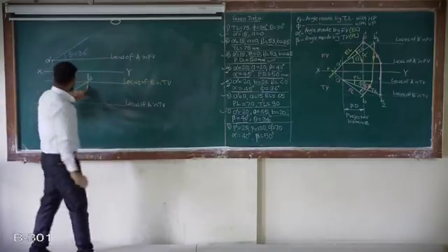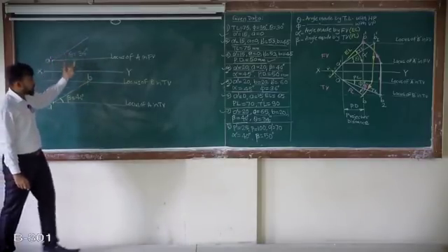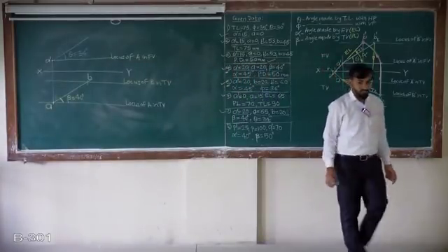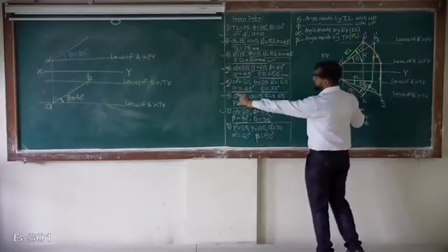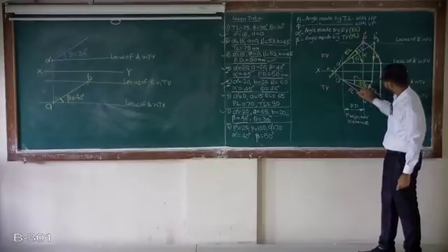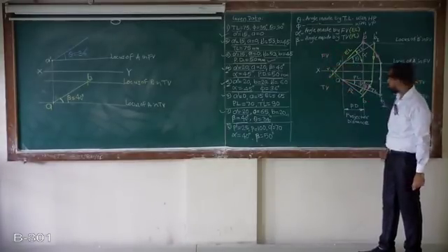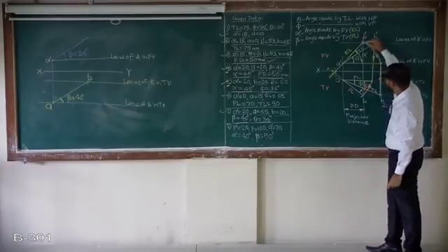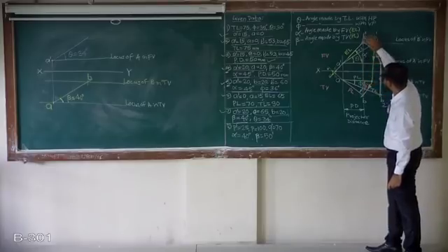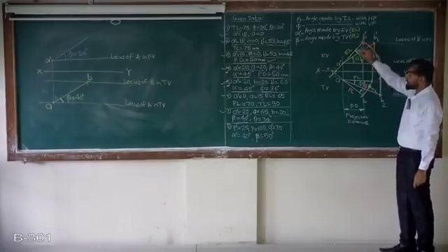Then see how to get true length, see, we don't know this true length in this. So how to get locus in the front view? By construction. So see here, I know this point B with the corresponding angle. So how will we get the corresponding point in the front view? First, what I can draw, how to get locus? First I can draw this locus, or instead of, sorry, not locus, it is projector. So draw the projector of B.